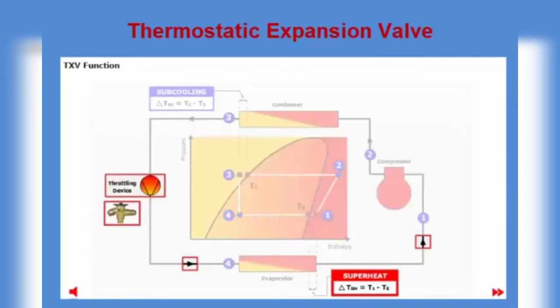This is where the TXV has a huge advantage. Because the TXV is a modulating valve, it will regulate the injection of liquid refrigerant in the evaporator in proportion to the actual operating conditions. This means it prevents liquid passing to the compressor independent of operating conditions.